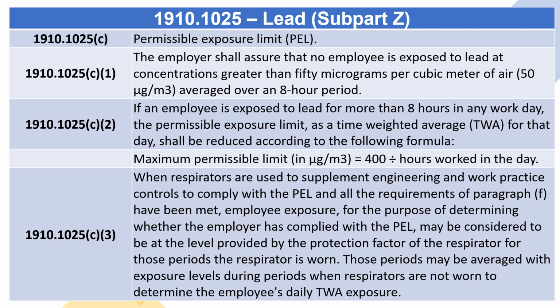1910.1025. C. Permissible exposure limit, PEL. 1910.1025. C. 1. The employer shall assure that no employee is exposed to lead at concentrations greater than 50 micrograms per cubic meter of air, averaged over an 8-hour period.